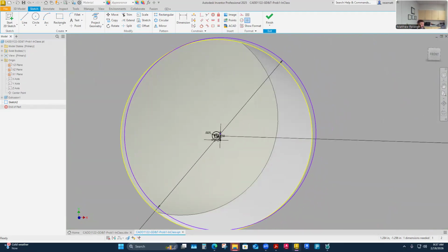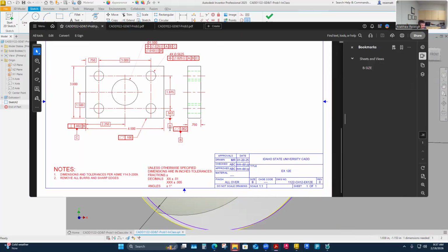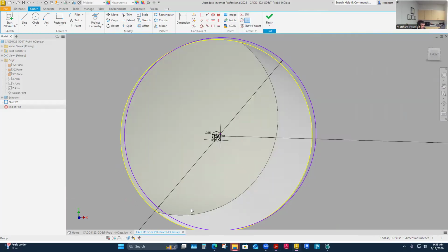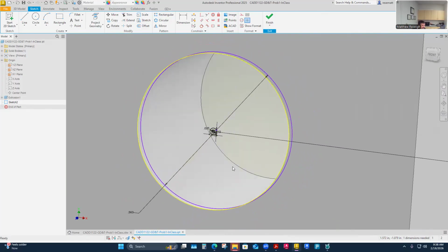So that's why, when I was watching some videos, I said I don't like these surface control tolerances. For one, they're quite a bit different from each other. And the other is that maybe this is too fine a control. Maybe 10 thousandths or 14 thousandths would be more realistic for a general purpose part. Or maybe no control at all, if it was understood that with a surface finish to some description, which we don't have any surface finishes here, but some of our GD&T stuff does. Okay.